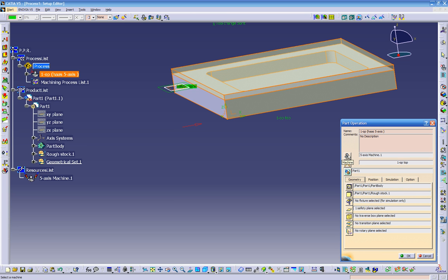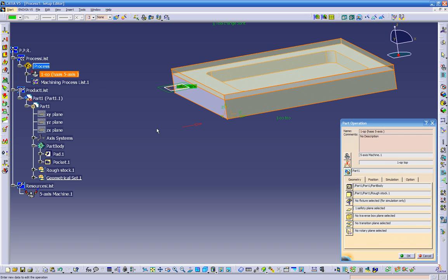So once we set up our machine, we set up our axis, we pick our part. That's why we have to make sure every time we create our part, that this folder is the part only. That's why we have to make sure not to have a whole bunch of geometry in one folder. So if this is one part, let's keep it in separate folders, because once we do the verify and we have, for example, on this level over here, a couple different parts, we're going to get an error once we try to run our simulation program.